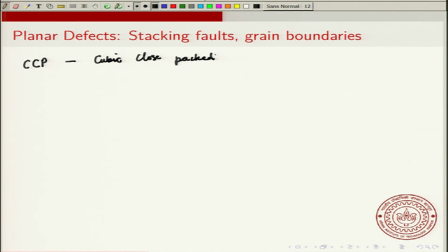So, that is a cubic close packed structure. You can think of this in the following way. You can imagine that there is a hexagonal lattice. This is the z equal to 0 layer. Let me mention here that this is FCC, and it is actually the 1-1-1 Miller plane. I haven't explicitly discussed Miller planes, but we will see that.